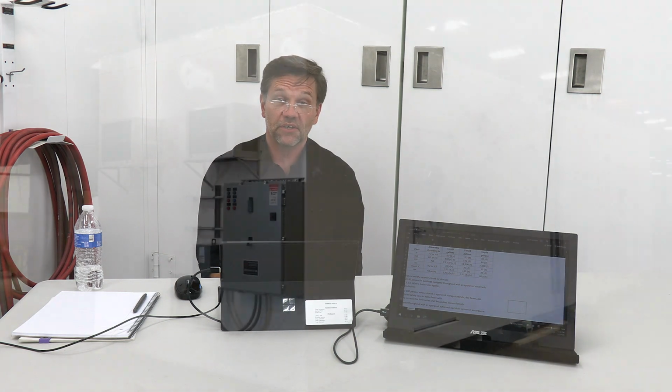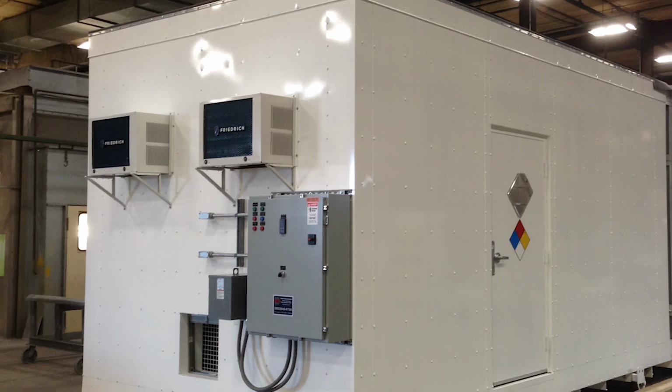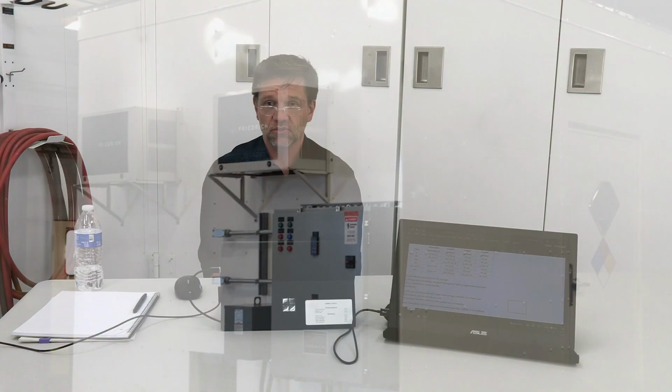The standard construction for GFS hazardous material storage buildings has not changed and will remain suitable for those situations where the interior is considered a Class 1 Division 1 location. We do offer some accessories such as air conditioning units that can be selected for Class 1 Division 2 locations within the storage building. But if needed, GFS can offer other air conditioning solutions where Class 1 Division 2 units are not suitable for your layout.